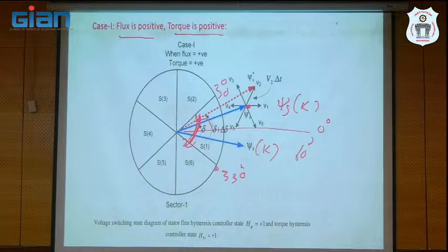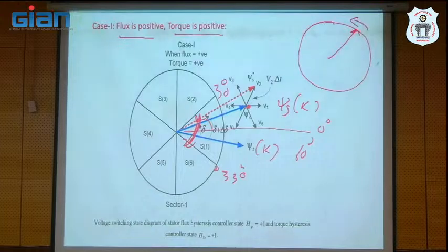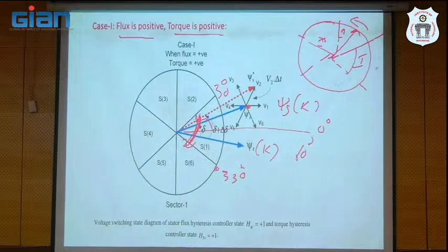Just a minute. I will show. See, your flux is rotating. This is the nature of magnetizing flux. It is always rotating with synchronous speed, right? So here what we are doing is splitting this total locus into 6 parts. That is up to you, right? We start here. We take this zone as sector 1, this zone as sector 2, this zone as sector 3. Deciding the sector number, angle, everything is under your control. You got my point? This is all our calculation.